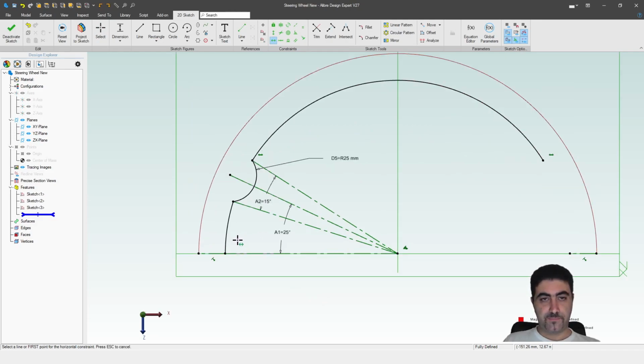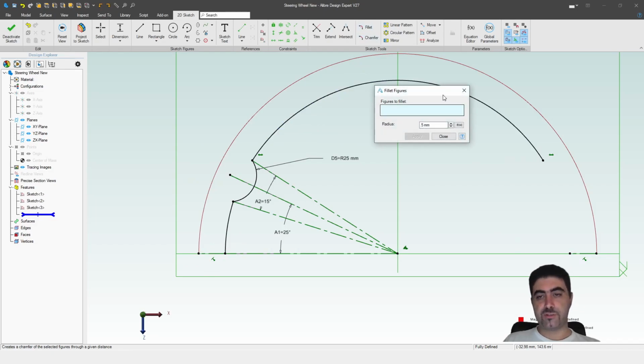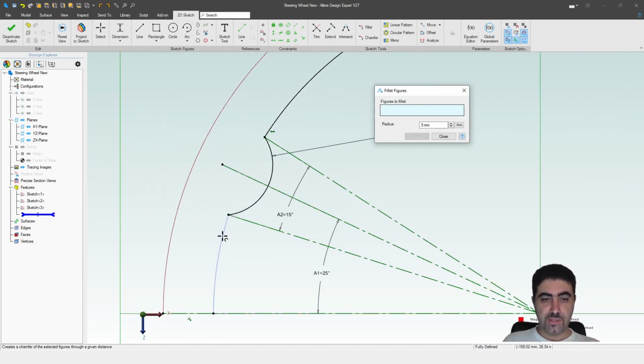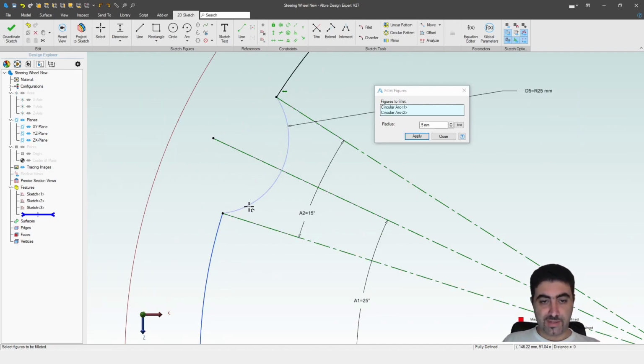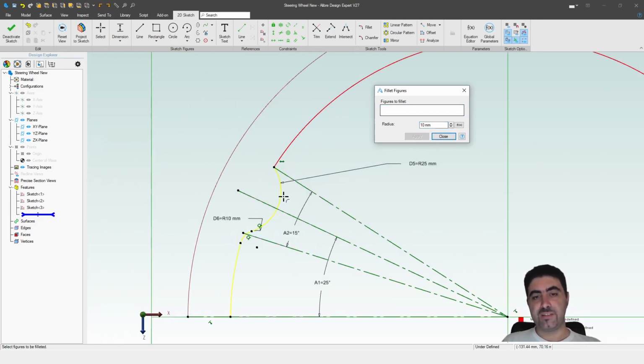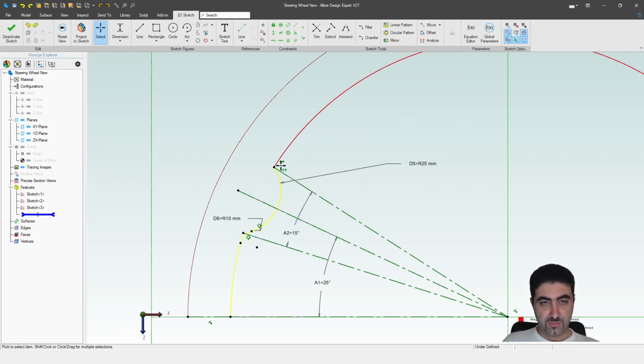And now, because this is going to be a guideline, I cannot create the loft and then fillet it, or at least I don't think it'll work very well. So because this is going to be a loft guide, I want to fillet while in here, and that's probably the only reason I would fillet in Sketch ever, right? Okay, that didn't go very well.